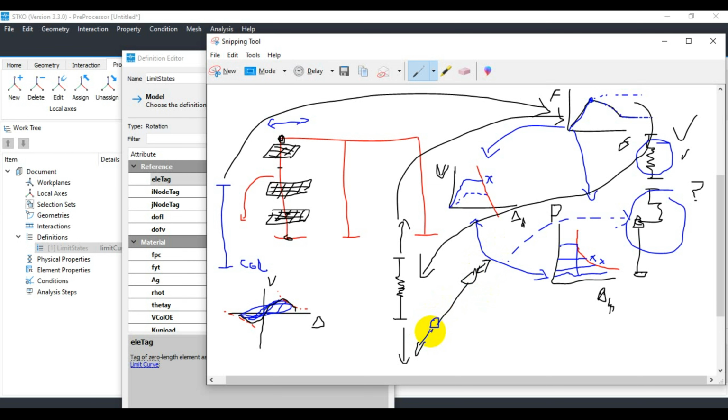In OpenSees, we have Steel01 and Steel02 materials, which incorporate further parameters in our analysis. The one-dimensional elements that I discussed here, the springs and truss elements, require only one uniaxial material to define their response. We can also use them for zero-length spring elements, with uniaxial material definition of the force-displacement relationship directly.